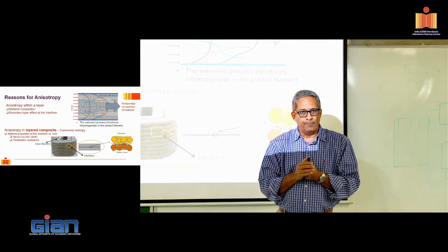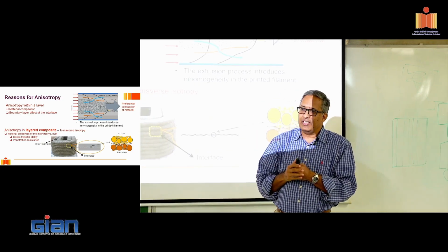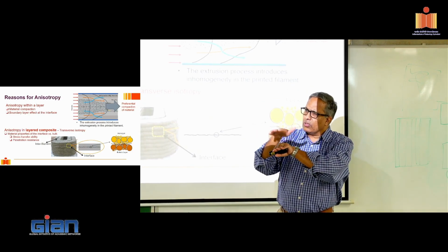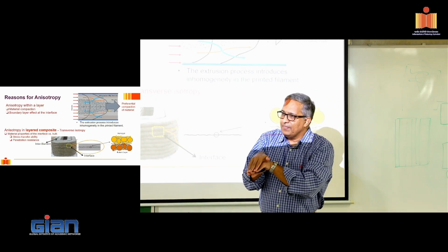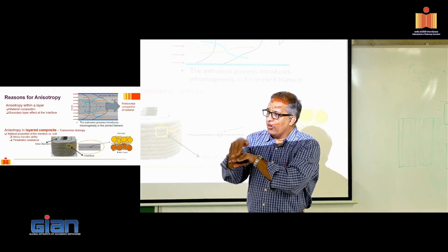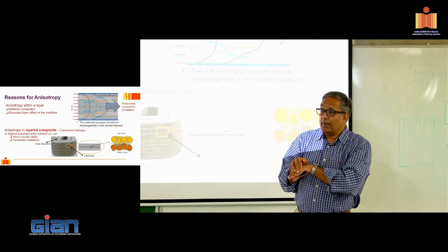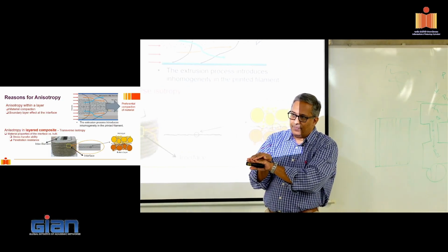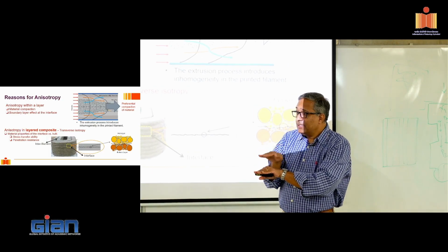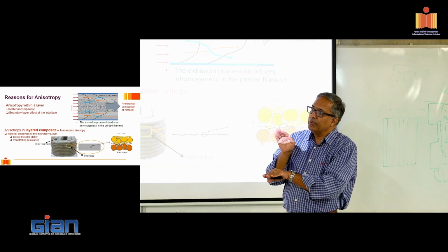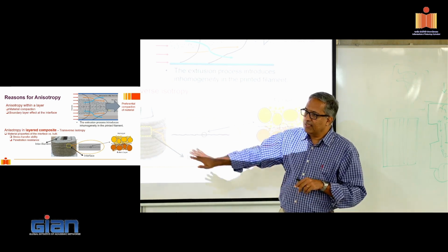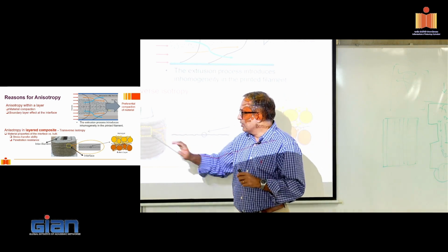That has to do with the aggregate. Now the next layer comes and it's also very stiff. What will happen? Those gaps will not close properly. And I'm not doing anything physically like vibrating it or pressing it, right? So what has to happen? Those gaps have to close naturally, right? But there'll be some gaps, and therefore what happens then? You basically start getting higher porosity at the interface, and you saw a consequence of that.